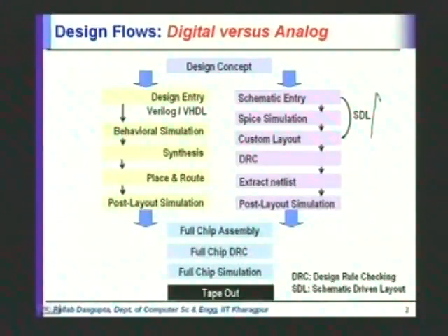So test means pre-silicon test, not the post-silicon test. So when you want to check a particular module, then the other modules are at the behavioral level, so that the overall simulation speed is much faster. Okay. So if time permits, I am going to talk a little bit about this in this course. And then the later part of both of these flows is the same, that after post layout simulation it's largely similar to the digital design flow.